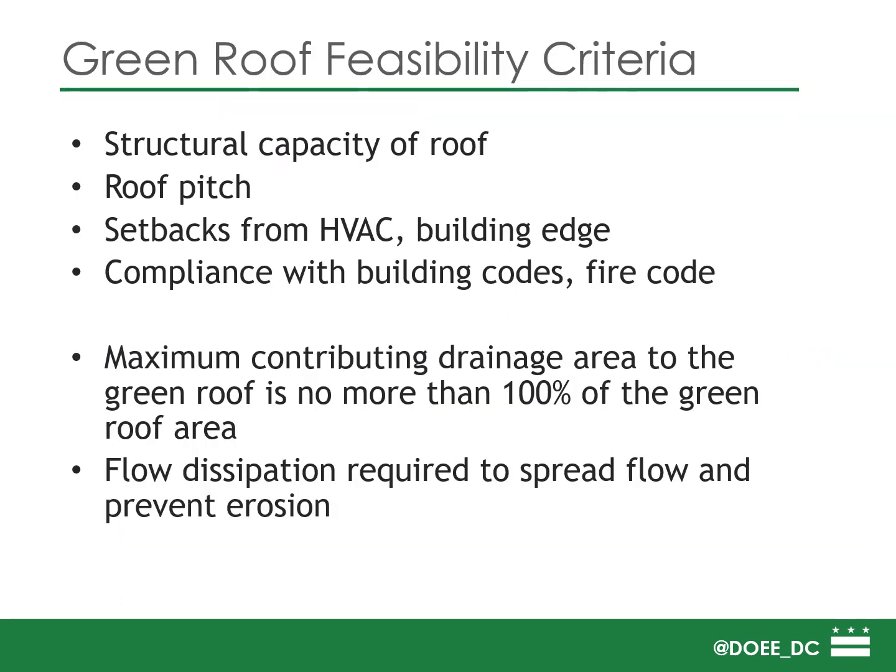So as I mentioned, the structural capacity of the roof is a consideration for the feasibility of the green roof. The roof pitch is also a consideration. Green roofs can be built on pitched roofs, but some adjustments need to be made to ensure that the media and the plants are not going to move. There are setbacks required from HVAC and other protrusions in the roof and from the building edge, and it must comply with all building codes and fire code.